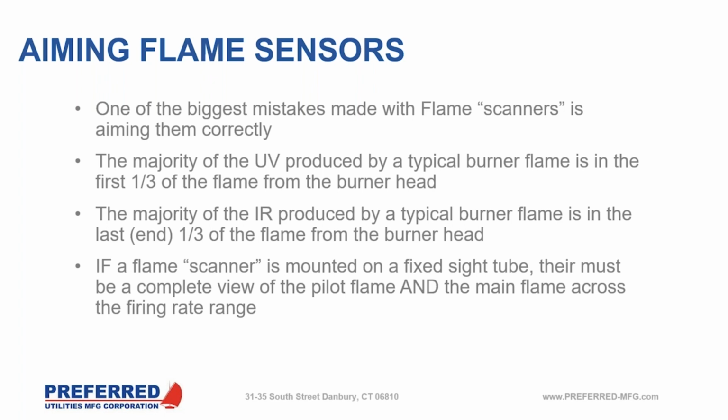Now, if you look at, for instance, UV, the majority of the UV produced in a typical burner flame is in the first 1/3 of that flame of that burner head. So being able to see a cross section of the base of that flame off the burner head is really, really important. And of course, seeing the pilot too.